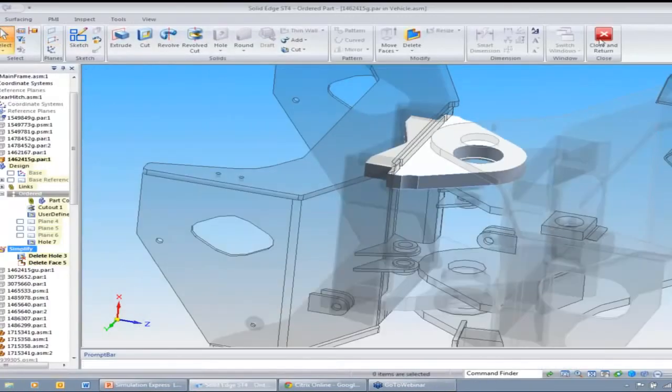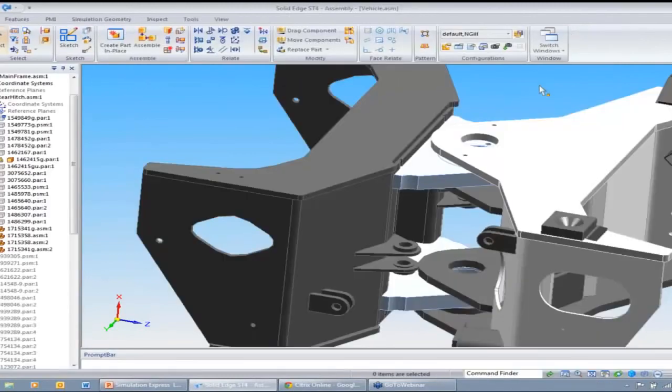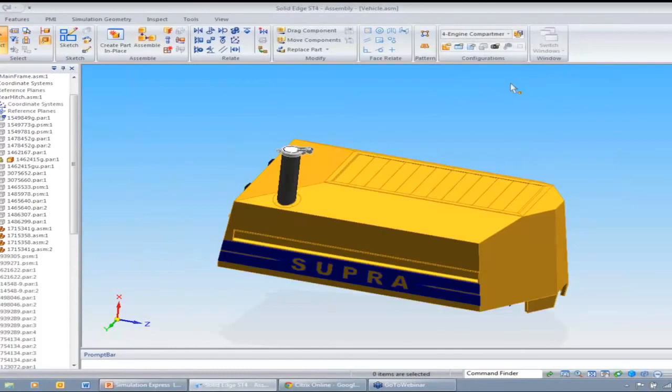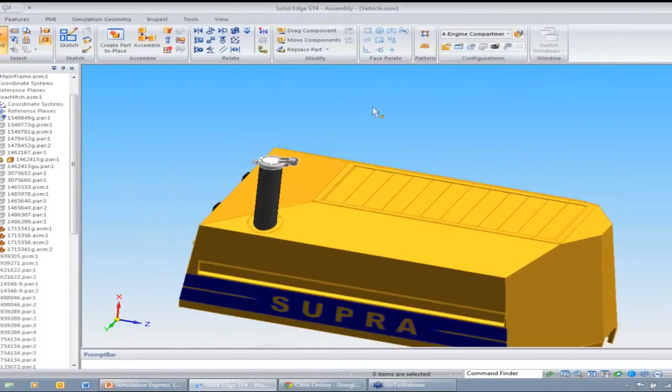Now, the next thing which I'm going to do is a different type of analysis, that is modal analysis. For that, I'll just activate this display configuration. We have this exhaust pipe here, and it's hooked to the motor. The motor is driving this heavy equipment, and it's going to withstand external forces such as vibrations from the motor. So we're going to analyze the part and calculate the first 4 natural frequencies.